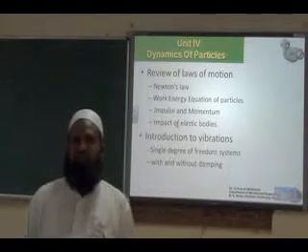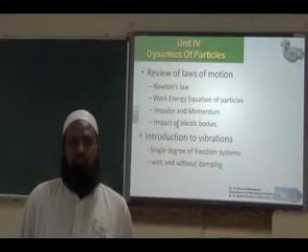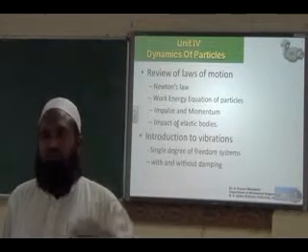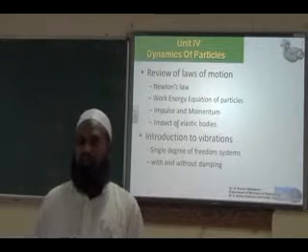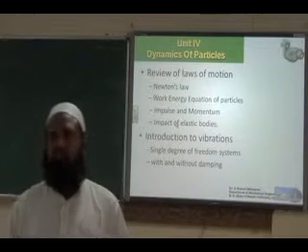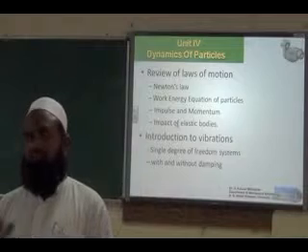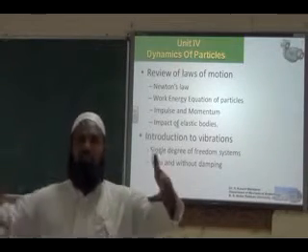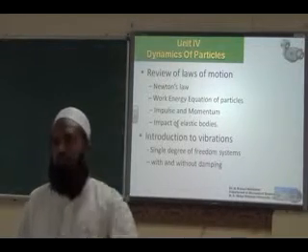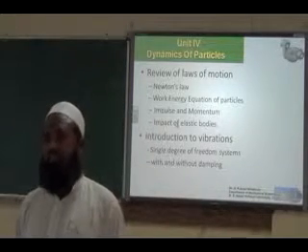Vibrations can again be classified into three kinds, according to the direction of application of force. If you apply the force parallel to the axis of the component, we call it longitudinal vibration. If you apply it perpendicular, transverse. If you apply it around the axis, then torsional vibration. So there are different kinds of vibration. Mostly shafts are subjected to torsional vibration. Springs may have longitudinal vibration. Beams, etc., will be subjected to transverse vibrations.